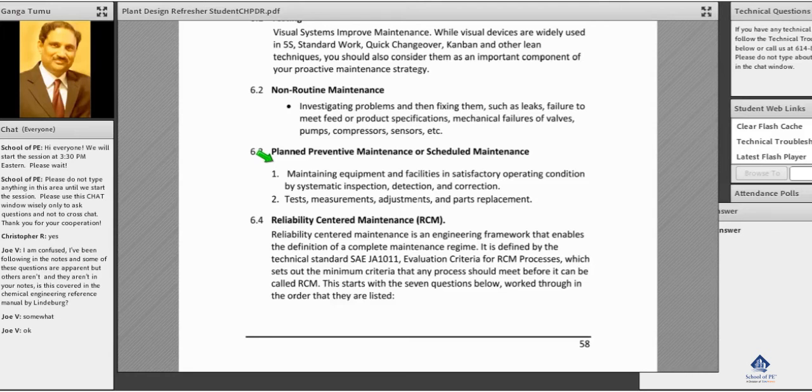If it is a glass-lined reactor or metal, they check the thickness of the glass. Also they do the spark test and look for any localized pitting, localized corrosion, or erosion. That way, when they further use the glass-lined reactor, they don't have a problem. That is the reason they do that maintenance every 6 months.